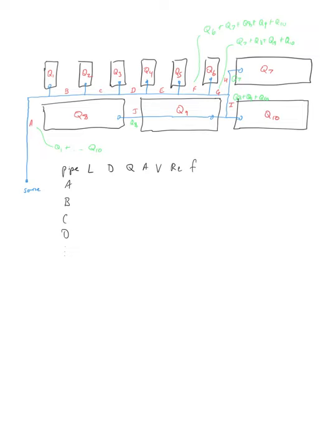And now we also have to consider minor losses, perhaps. The way I like to think of it is we have to decide whether we're going to consider minor losses or not, but we have to decide intelligently. So at some point we need to calculate what some minor losses might be, compare them to the major losses and say, are they going to be significant or not? If we're going to include them in our analysis, we might have minor loss coefficients that occur along that pipeline. And then finally we'll calculate the major losses and the minor losses that occur on each line.